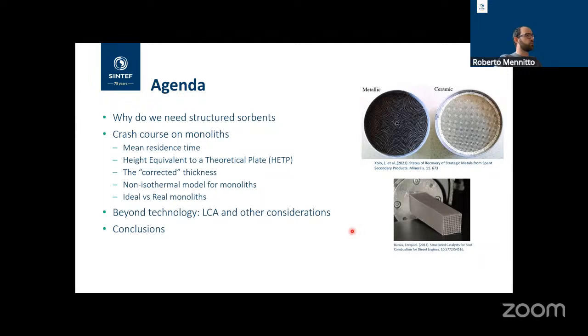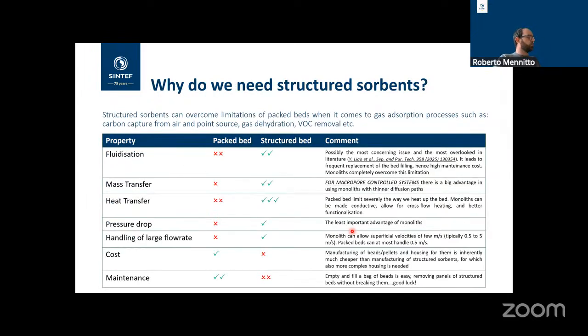So let's look at why we need structured sorbents. Especially in recent years with the boost in direct air capture R&D, it's very easy to say that structured sorbents are a very good solution compared to packed beds, but actually packed beds tend to work rather well. Given direct air capture, the first benefit we could think of when it comes to structuring a sorbent is the very low pressure drop and the handling of high flow rates, which is of course a benefit, it's a fact. But I would like to challenge the status quo a little and say that possibly pressure drops and flow rates are the least appealing benefit that structuring a sorbent can bring to the system.